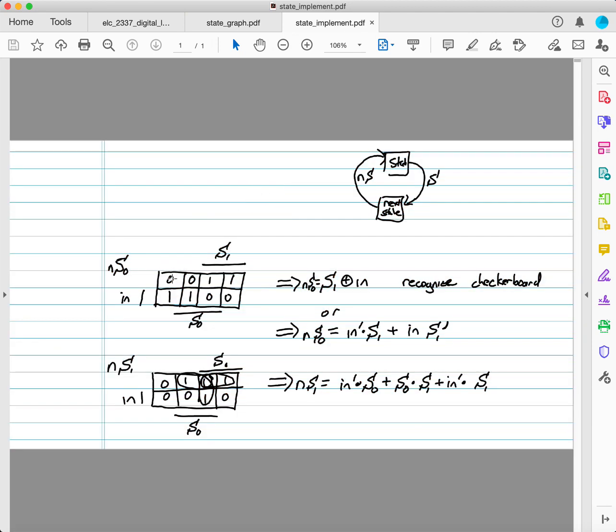All right, now I could look at this. We've just explained where the first table came from and the naming conventions. We'd already copied this one in, right? Remember, it was 0, 1, 0, 1, 1, 0. Don't forget, you have to go to the outside, the far column, 1, 0, because this is set up in that gray code style order. I could just look at this and recognize this checkerboard pattern, right? Zeros, ones, zeros.